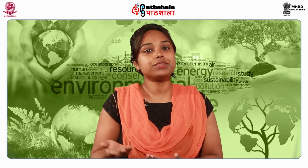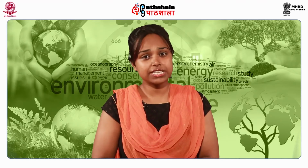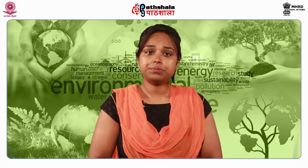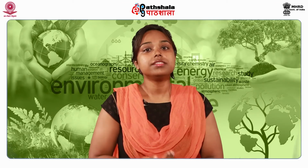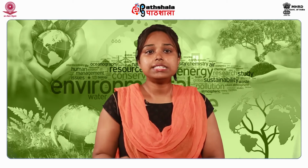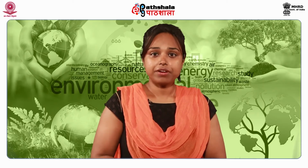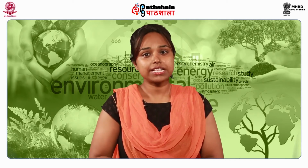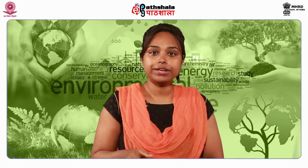Starting with the introduction to waste treatment. The processes such as stabilization, solidification, fixation and encapsulation are some of the remediation techniques used for the management and disposal of a wide range of hazardous waste. In these processes, the waste is immobilized using different chemicals or additives. The contaminants are also encapsulated in a medium to stabilize it. According to Environmental Protection Agency EPA 1989, the process of solidification and stabilization makes the handling of waste friendly, easy and improves the quality of waste.